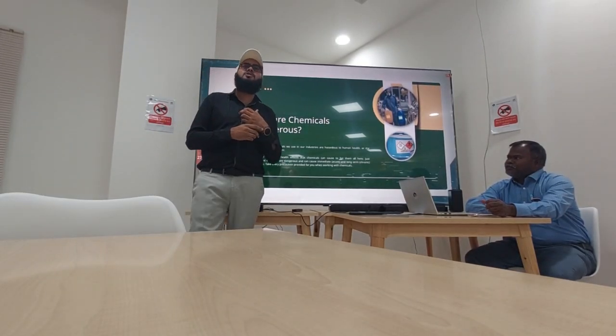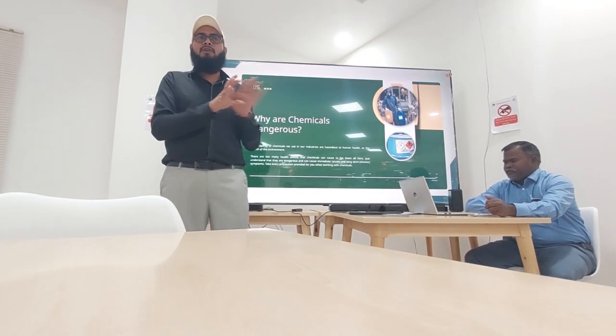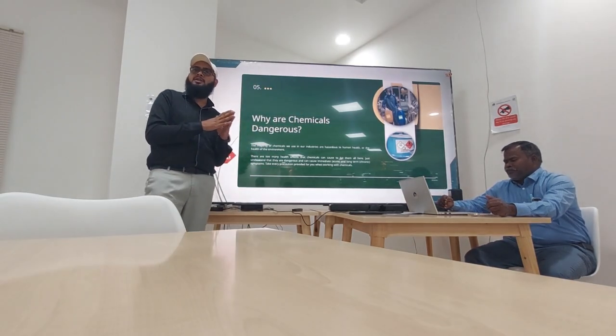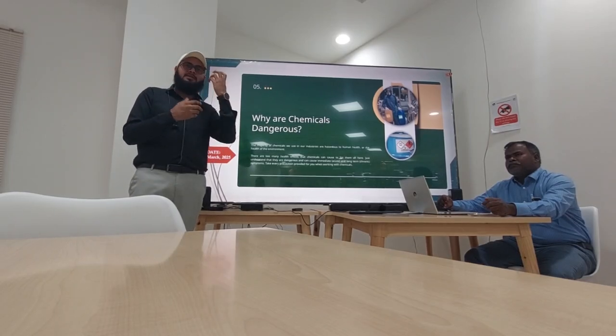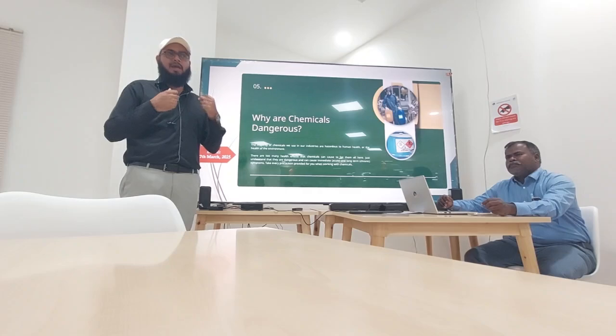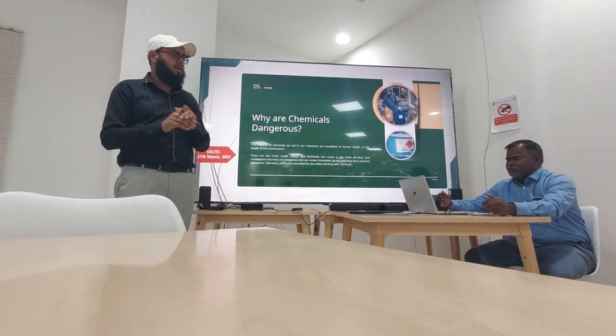So you should know the consequences of what you are using. Otherwise, you will not take care properly. So that's perchloroethylene. When you are using it, have proper PPE, starting from a mask and then other PPE if you have it, that is good. But otherwise, a mask is mandatory. Mask and gloves are mandatory.